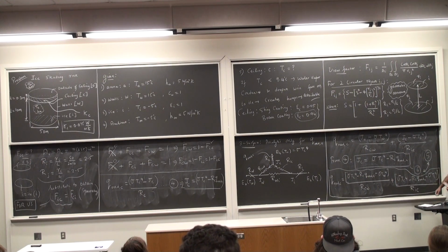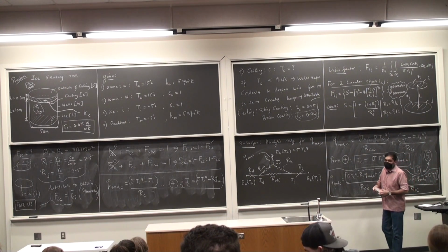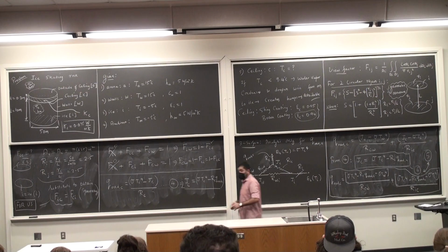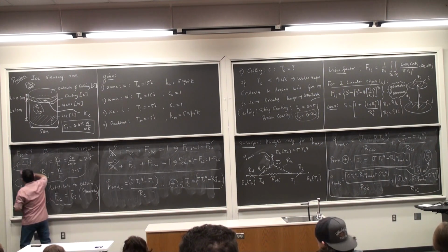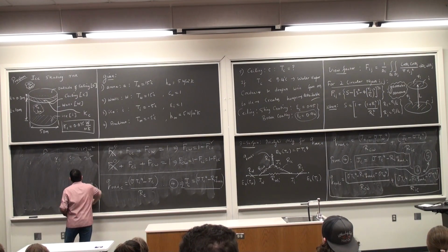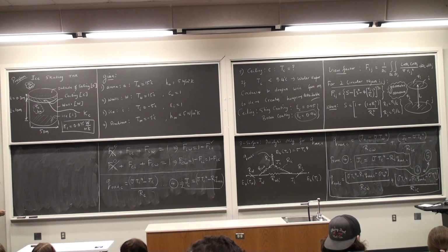So, what you will see is that if I take this equation, I will have to calculate this 2 times because the emissivity of the ceiling has 2 values. One is 0.05, the other is 0.94. So I'm going to get 2 iterations of this particular equation. I'll write down the steps and then we'll come back and finish it off. I'll post the entire solutions as well for you to see if you'd like. Couple more minutes and I'll leave you for the day. We still have the semester to finish.